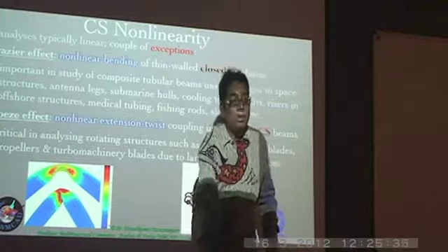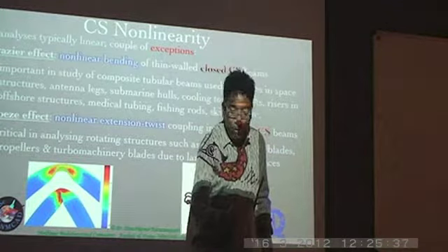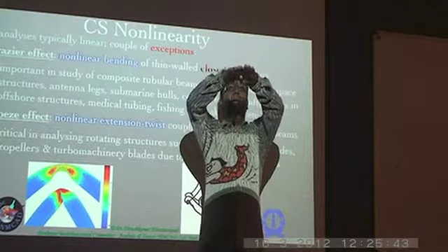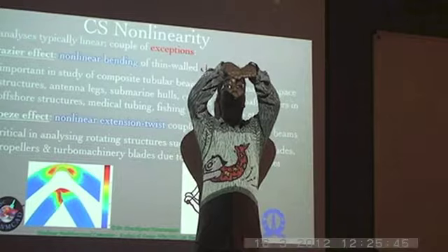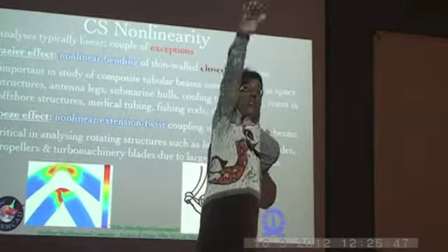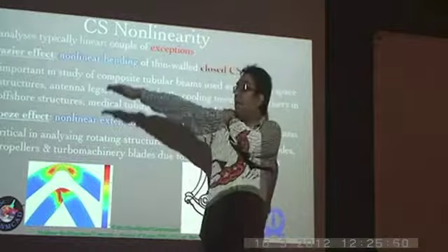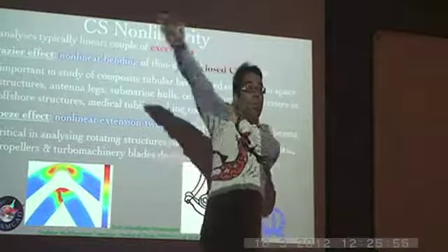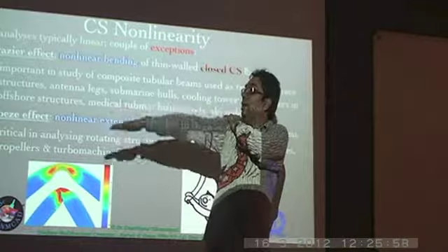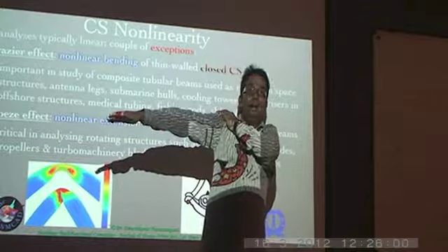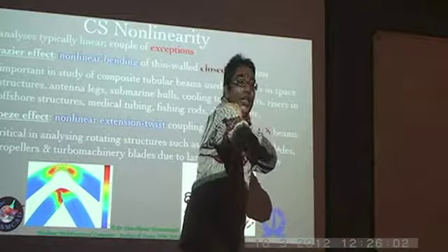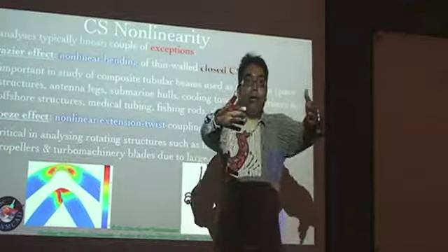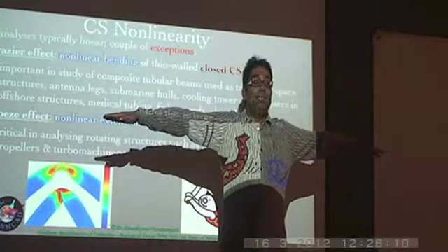On the other hand, when the pilot is, let's say, moving the cyclic pitch forward, the rotor plane has to tilt forward. The way that happens is because of the flapping motion of the helicopter rotor blades. As the rotor blade goes around the azimuth, it also has a flapping motion, and this flapping motion has to be periodic: at this location it has the minimum flapping, at this location it has the maximum flapping, and at these two locations it's somewhere in between.